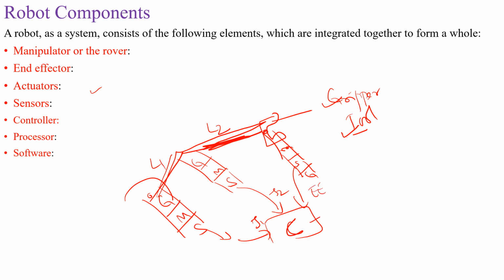Inside you have a set point database. For example, joint one has a different set point. So both are compared, and then it takes a control action. The voltage given to the motor produces the mechanical motion. Mechanical motion means, suppose the link is here, it makes the link move through this much angle. That is decided by this controller output.